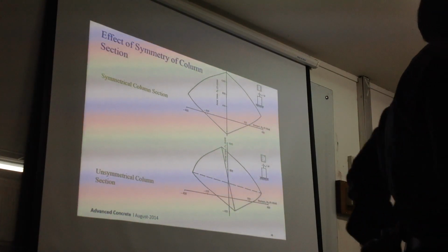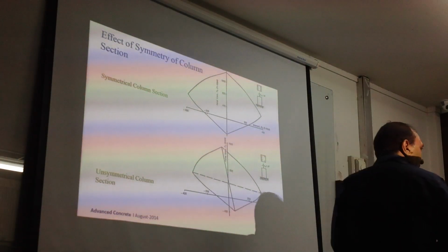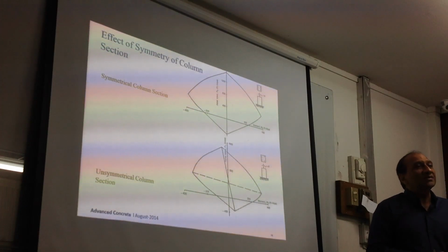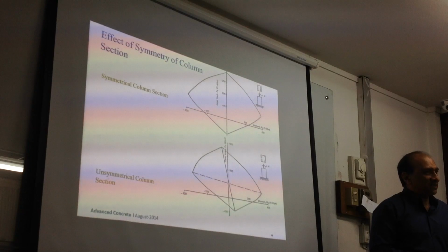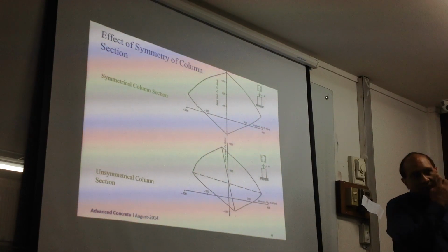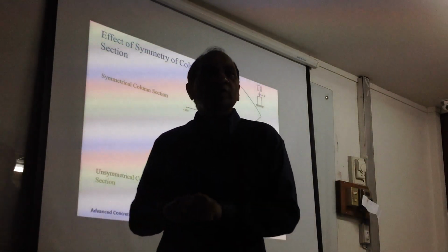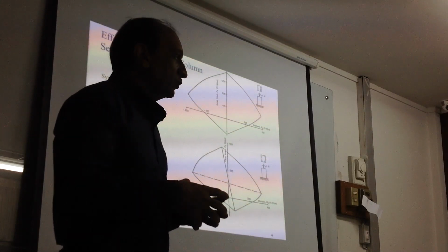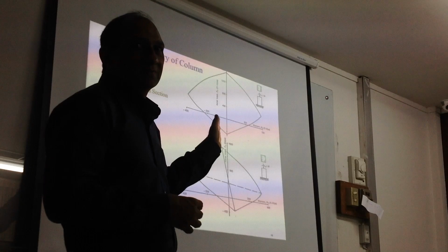That will become the transformed geometric centroid, right? So that transformed geometric centroid is like a plastic centroid, which takes into account the difference in the material properties also. So if you put more bars on one side, that centroid will shift, right?